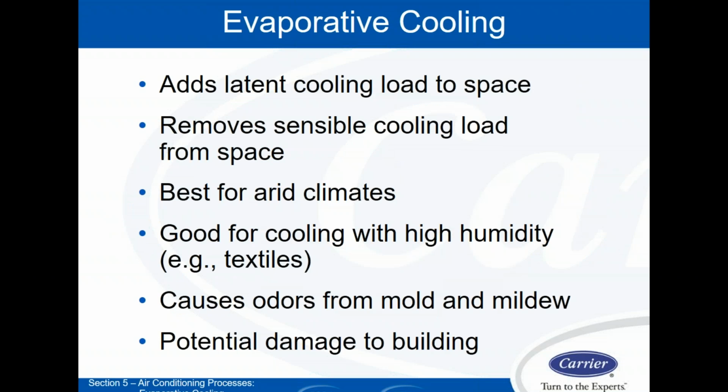So obviously, when I do this, it adds latent cooling load to the space. It removes sensible cooling, but it adds latent cooling. I'm swapping one for the other. As mentioned, it works good in Arizona and other dry climates, sometimes also manufacturing. Sometimes the humidity actually benefits certain manufacturing processes, so it works good in those cases. It can have more increased issues of mold and mildew, so these have to be very well ventilated spaces if you're going to be doing this, or extremely dry, like, once again, Arizona.